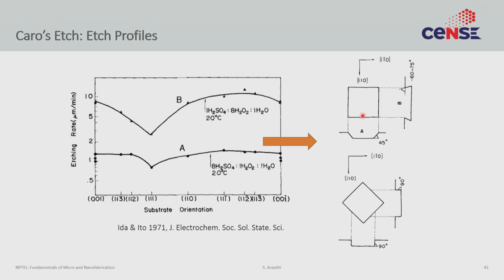So if you look at the same square, but in the cross section looking from this direction, which is the 110 direction, you would actually get again a positive slope. So you see the complexity of the anisotropic etching, and the cross sections that you can get are significantly more varied here in gallium arsenide than in silicon, and that is because the crystal fundamentally is more complex. To make sense of all of this and actually visualize this in 3D becomes a little complicated. That's why you have to use simulators, and there are now simulators that actually help you align and think of these things in 3D.